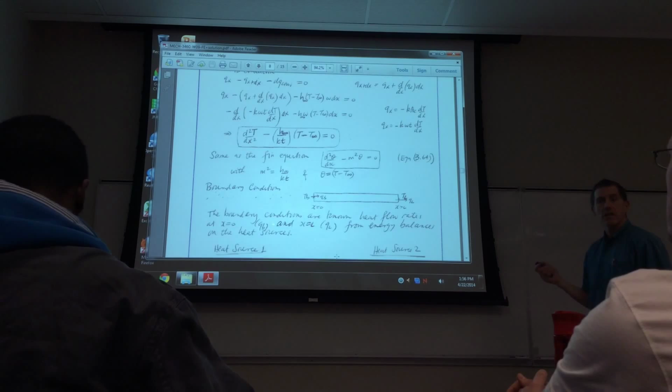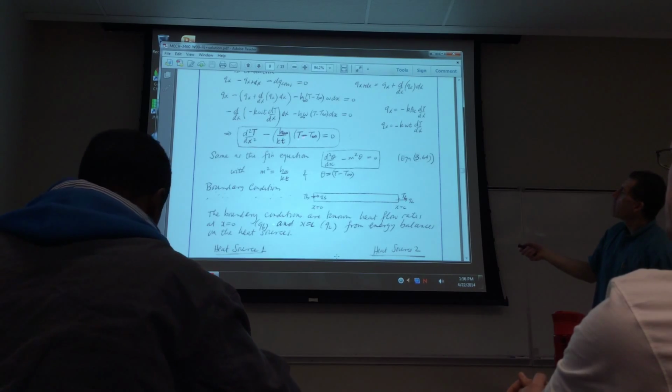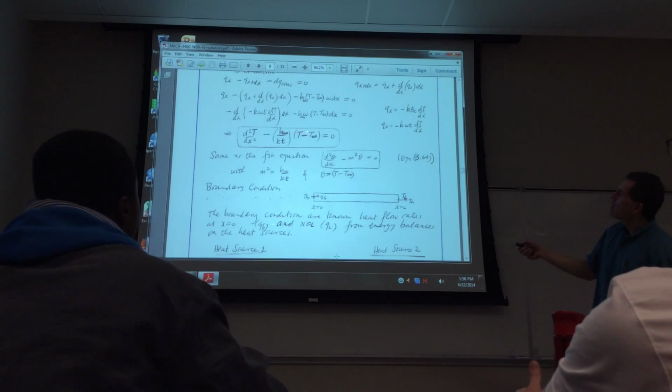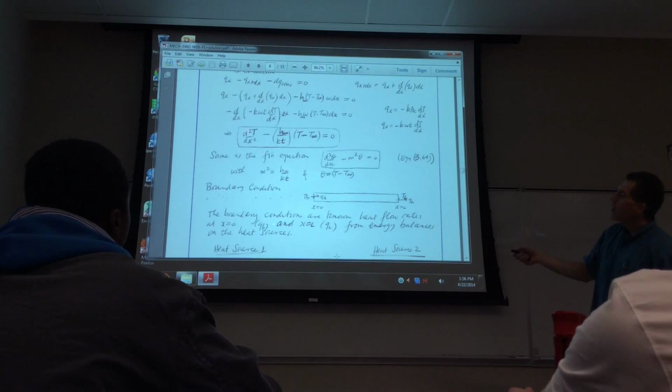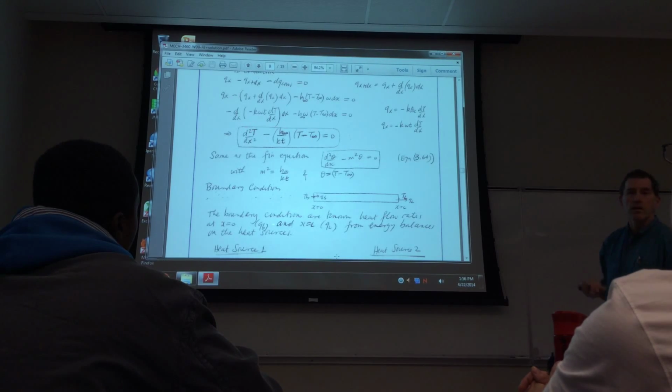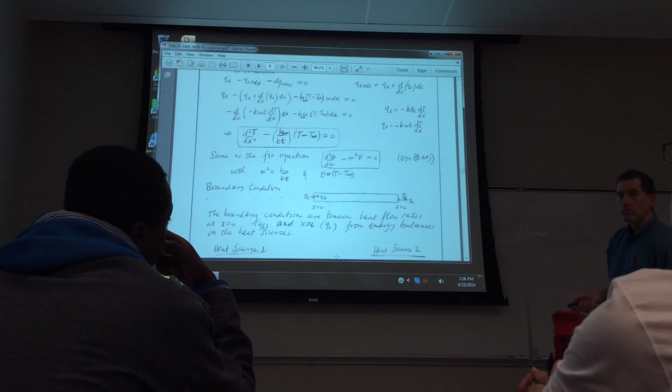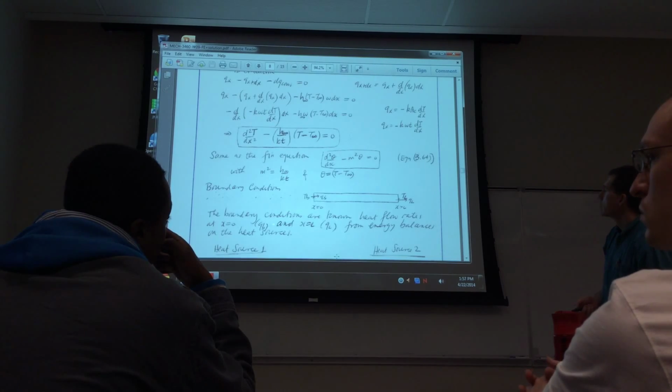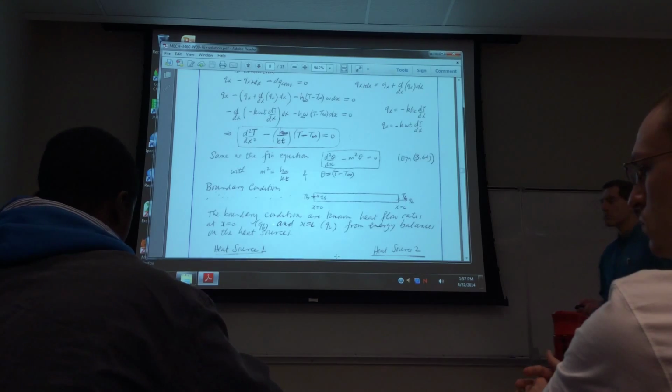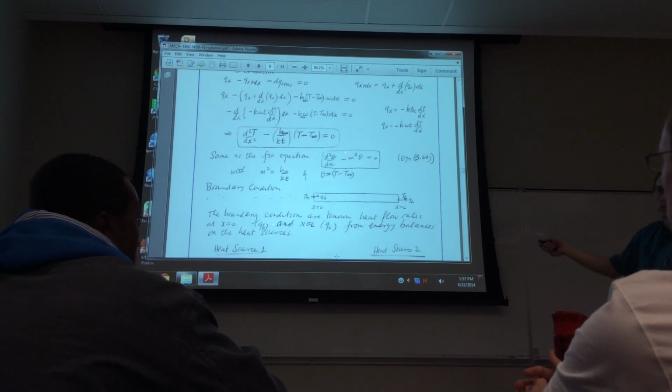Another important thing to recognize here is if you get an equation that looks like this, T minus something on this side, and you have a T here, you can convert this into d2theta/dx2. So you don't have to leave it in this form if it's causing you problems. You can make this a theta, and you can make that a theta without changing the equation. At that location, equation 3.64, could you say that the solution to the second order is just like C1 times e to the negative? Yeah, straight away. As soon as you get here, you know the formula solution.